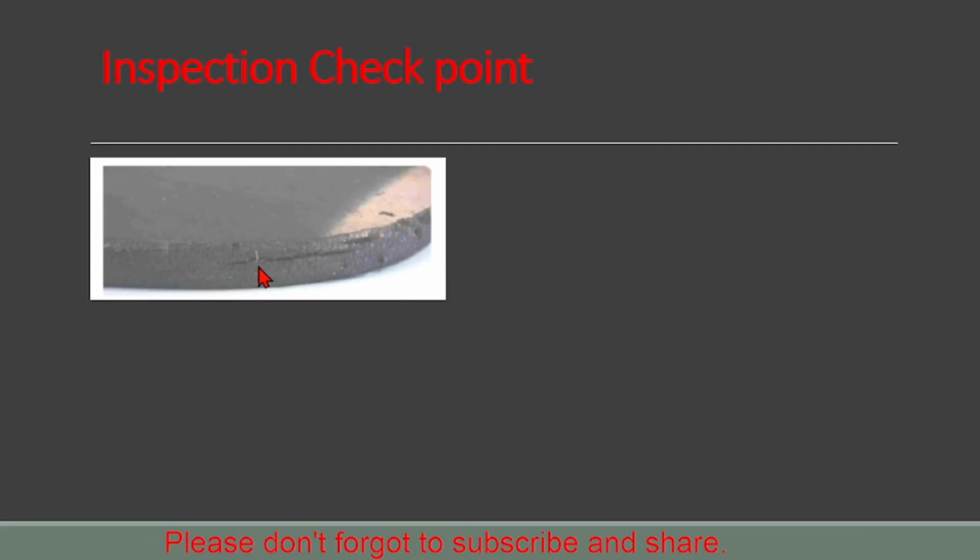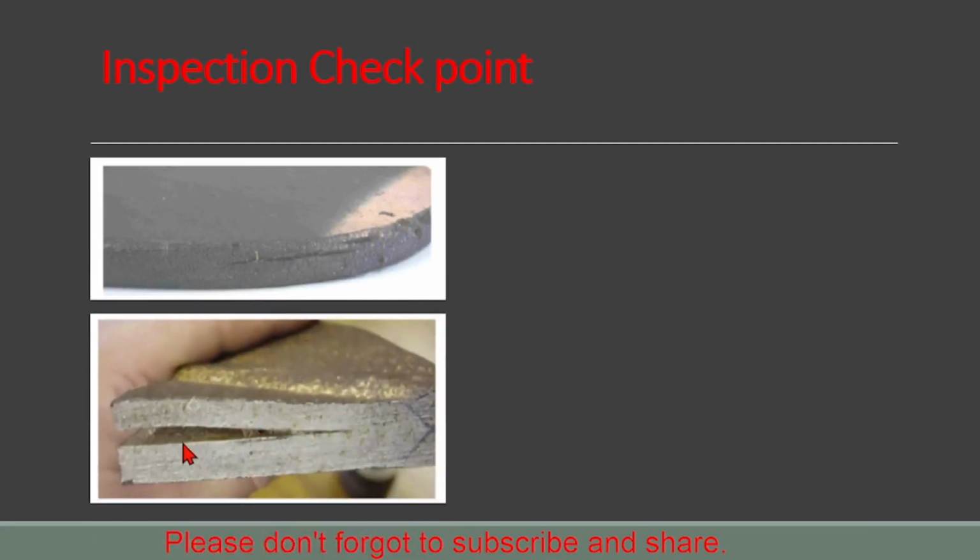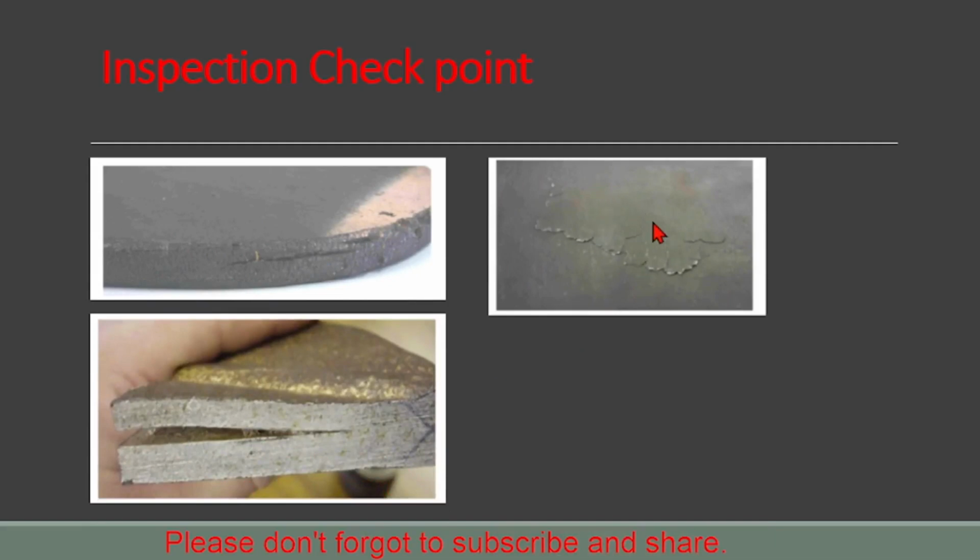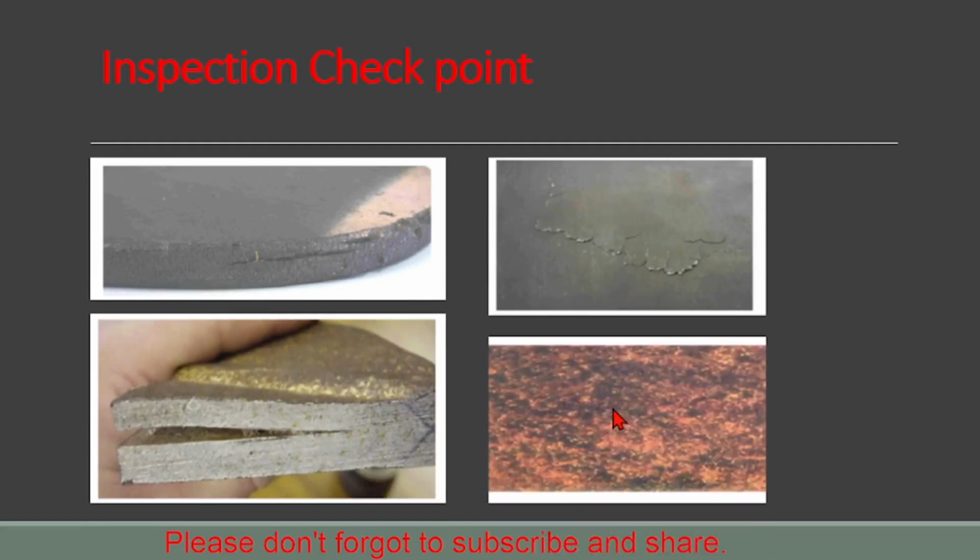Then we can see here is one lamination. So lamination is like that. So we can see the lap on the surface. So this is the lap, this is the corrosion. So you can see the surface, how it is corroded. So we have to check our standard for the things we can accept for corrosion. So lamination is totally not acceptable, and lap also. So we have to check our project documentation, how we can resolve this. So these are the things we have to check during visual inspection, material incoming inspection, and we have to record the things.